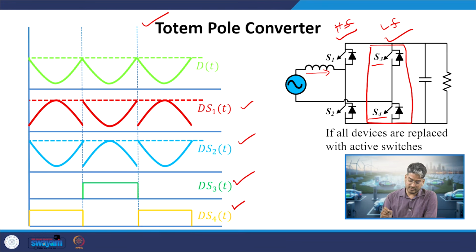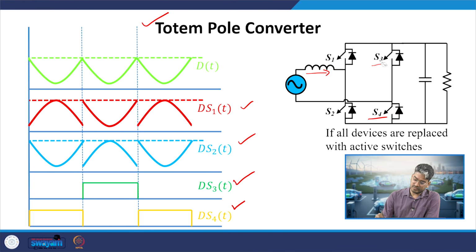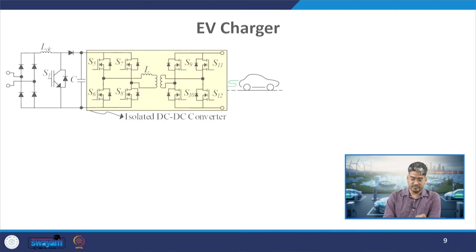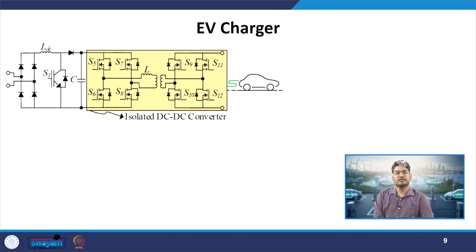at high frequency. So, the next solution for this will be your active full bridge converter, where we will come back to this circuit again. There we will see that both legs will be operated at the switching frequency. So, we will see the advantages and limitations of the active front end converter in the next few slides. Okay. So, before going into active front end converters, or converters made with fully controlled devices, we will see the 2 solutions which we have already discussed.